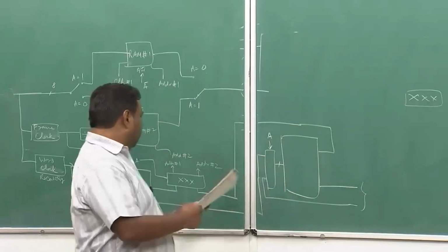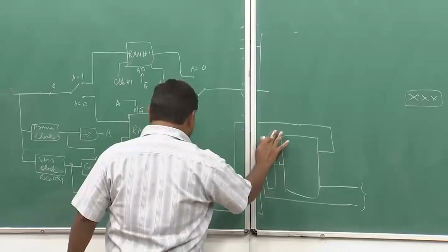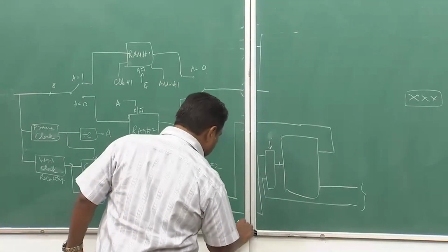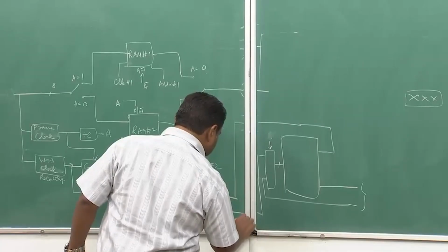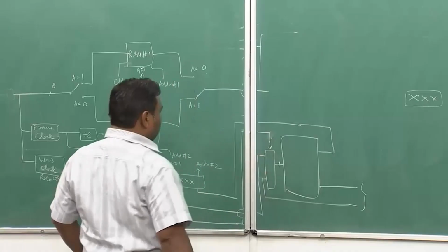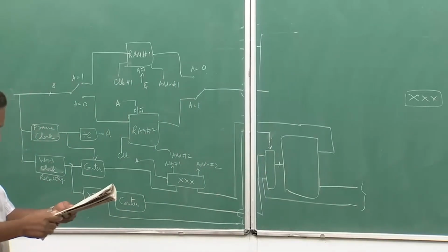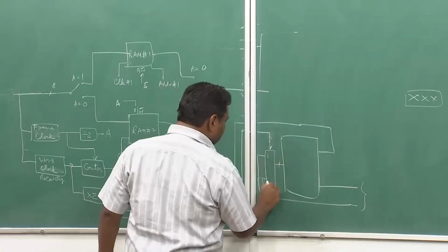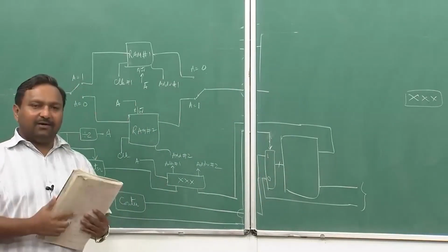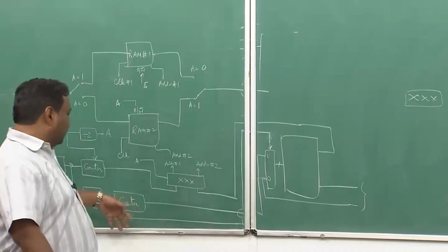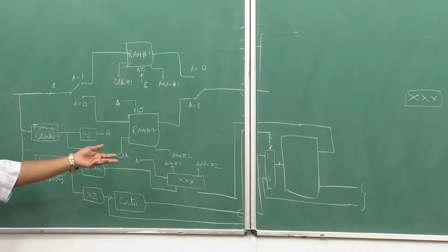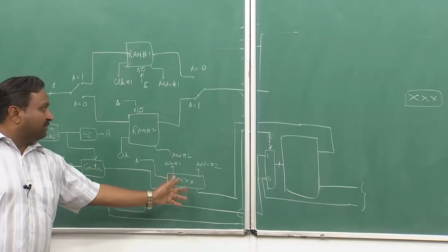So in one half this will be acting for reading out, in another half you can write into this control memory. So in fact I should not connect A here, I will actually be using this double rate clock which will come here. So, in one half, when the double rate clock is positive, I will read out, in the second half I can write into this, but this is being triggered at double the rate and it is reading all the time. Okay. So the only thing is the flip over will happen between this.